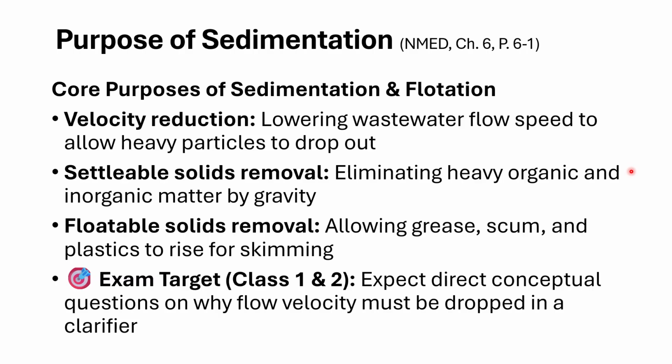Okay, so, purposes of sedimentation. Recall that in our sedimentation basin or our primary clarifier, what we're trying to do is get the heavier settleable solids to settle down into the sludge blanket, and the organics, the fats, the oils, the greases, if you will, we want them to float to the top where we're going to have a scraper, and direct that into a trough, a scum trough or a scum box, okay?